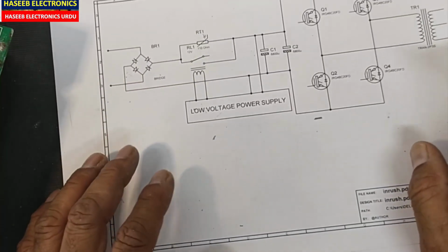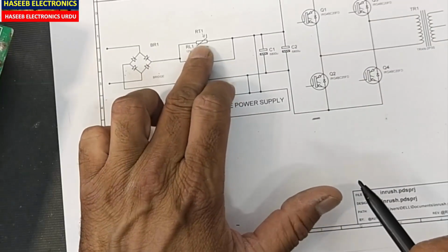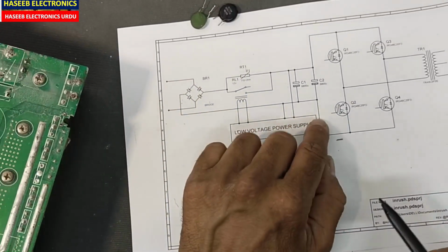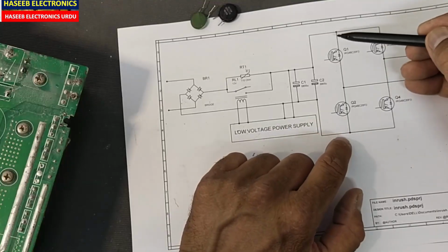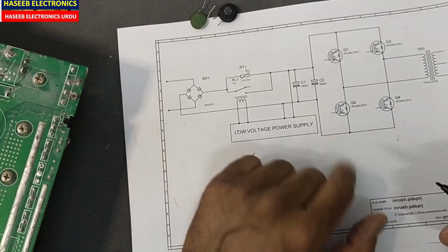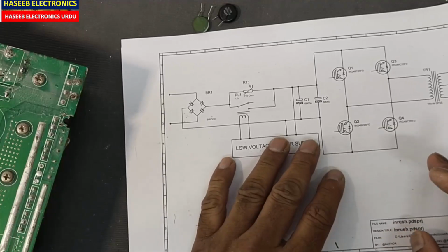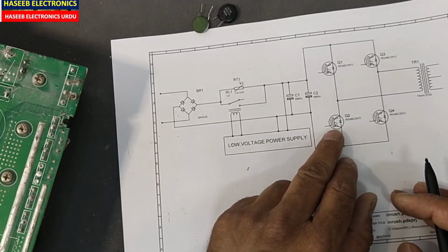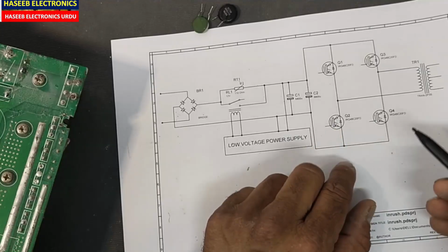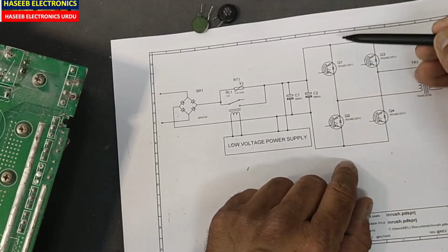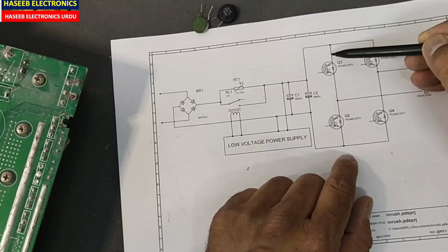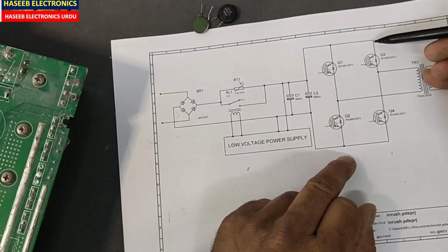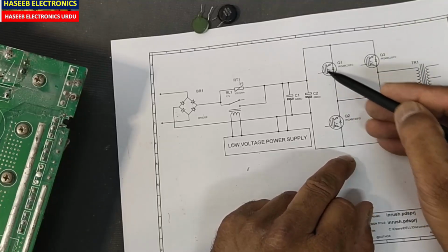What are the possible reasons for this PTC blast? There are three possible reasons. The first: we have high power switches, that are IGBTs here. Most of the time it is in push-pull stage, H-bridge configuration, any configuration. We can see one IGBT is at the positive side, the second IGBT is at the negative side. Same here, positive, negative. So these will switch in cross.